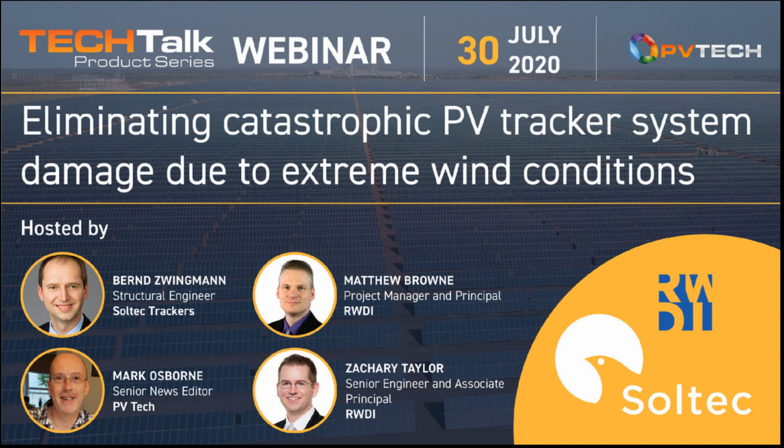Yeah, so this is Zach here. The animation that you're referring to, I think, is the one with the pressures applied. And so in that case, we exaggerated some of the rotation. So that's a buffeting response. So that could be below the stability limit, as Bernd discussed. These are flexible systems, and in a turbulent wind, you can see a lot of motion. And so it's important to understand the loads associated with that motion so that you can design accordingly.